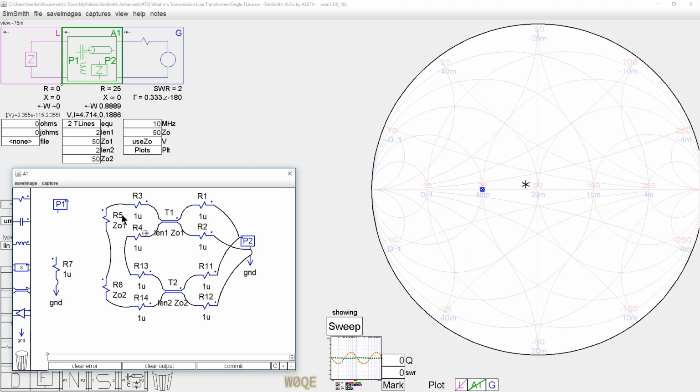Now what we did is we stacked up these 2 on top of each other. We stacked up the resistances. We stacked up the voltages on the output of the transmission lines, and both of them are in phase, and we still have 25 ohms.